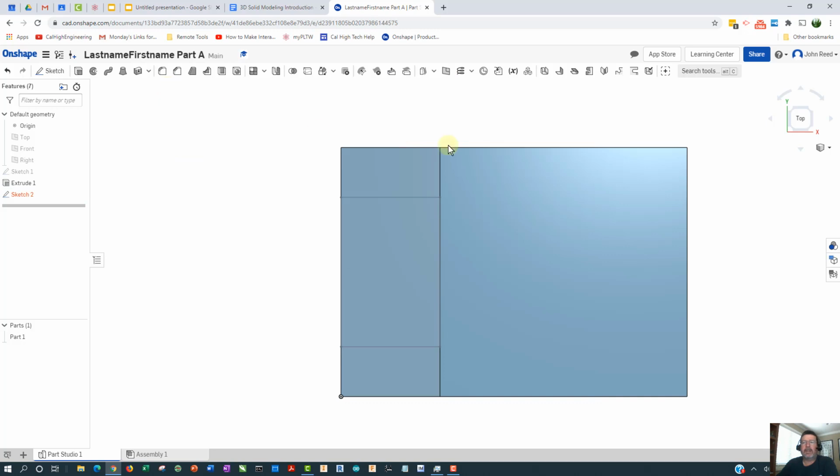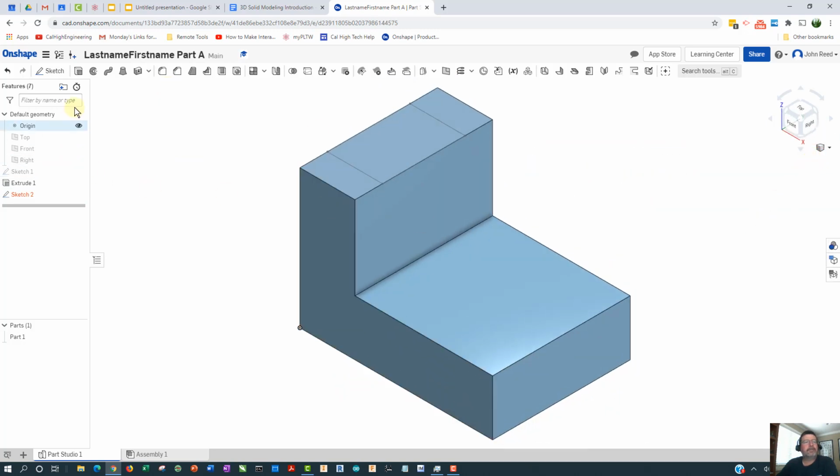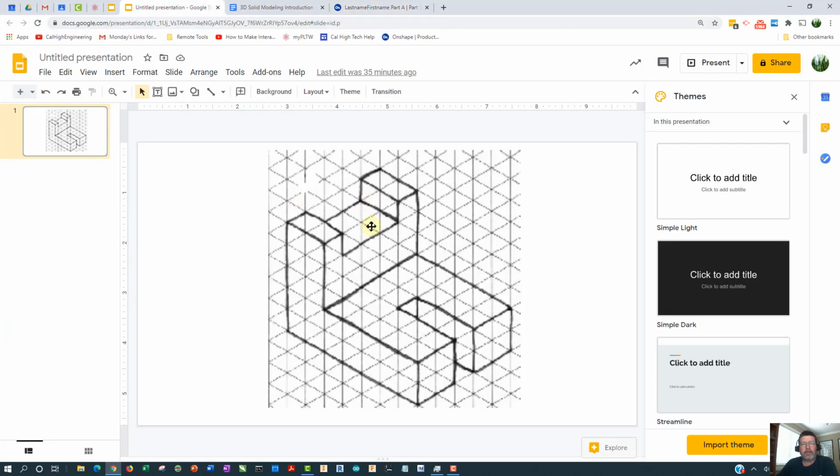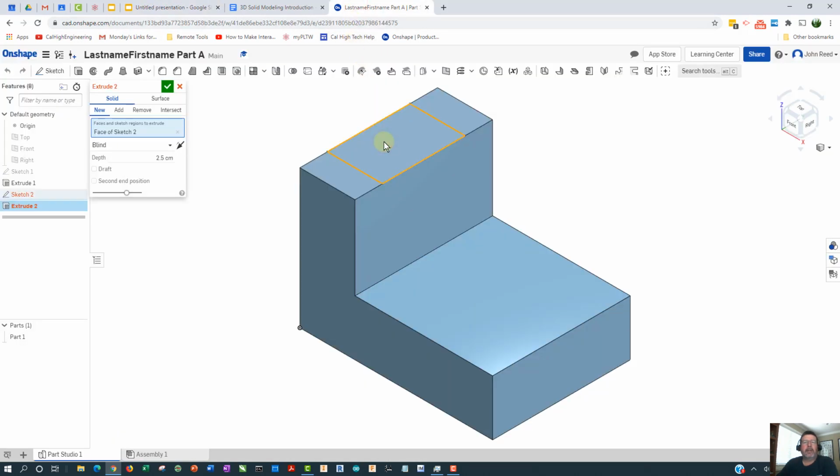So I'm going to finish that sketch, come over here to isometric, there it is, use the extrude tool right here again, Shift E or click this button. Now here you've got to be careful. I want to remove material here. As you can see, I want to come down 1 unit. So I come over here and I click there.